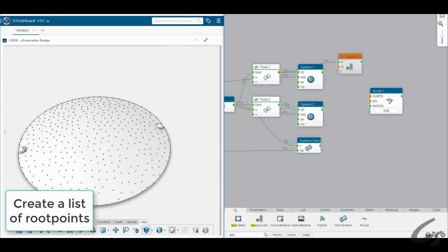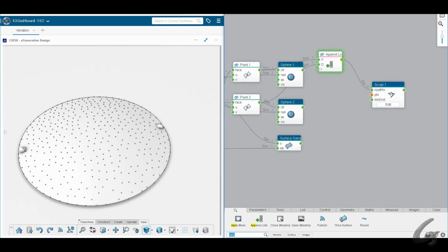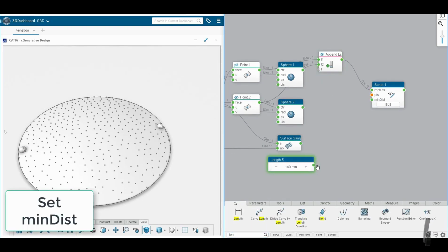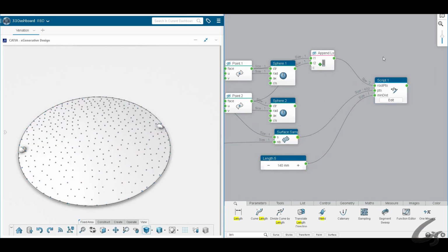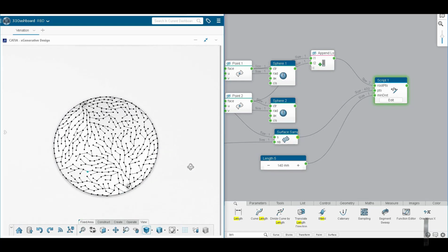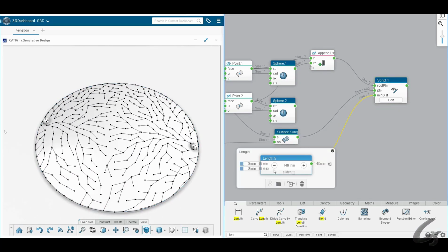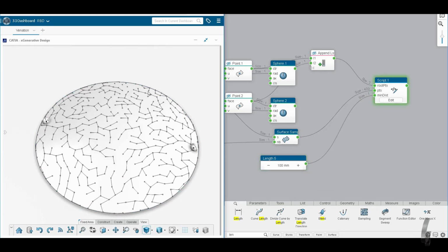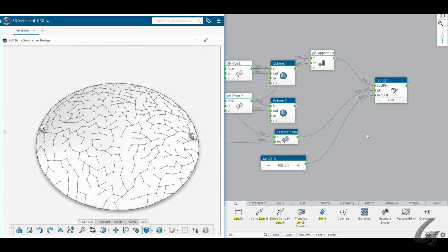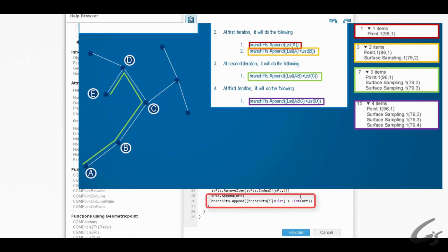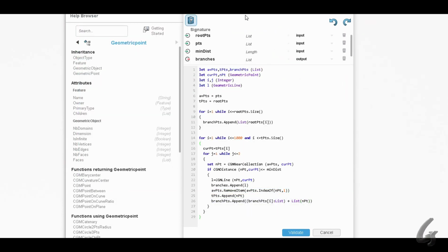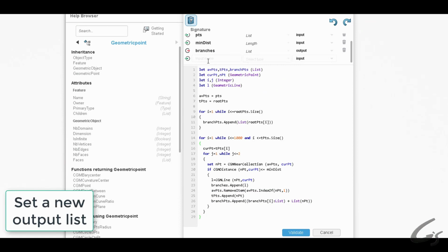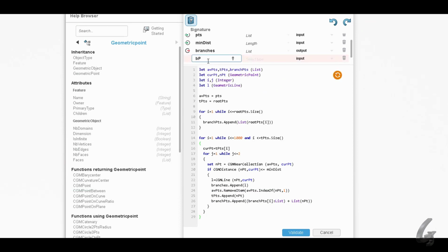Now we can try and play with this script here. We can connect it to different parameters with the points, inputs, and the script starts calculating. We can now start playing with different values and parameters to see if we like the pattern, if it's too busy, if it's fine. What we can now do is start adding more polylines to the script. The aim is to create a polyline linking all the points to their origin passing point.